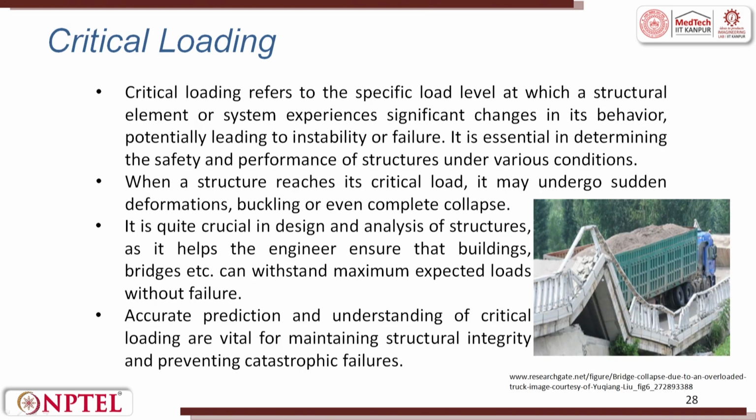Critical loads. Critical loading refers to a specific load level at which a structural element or a system experiences significant change in its behavior, potentially leading to instability or failure. It is essential in determining the safety and the performance of structures under various conditions. When the structure reaches its critical load, it may undergo a sudden deformation, buckling or even complete collapse. Critical load is very important.